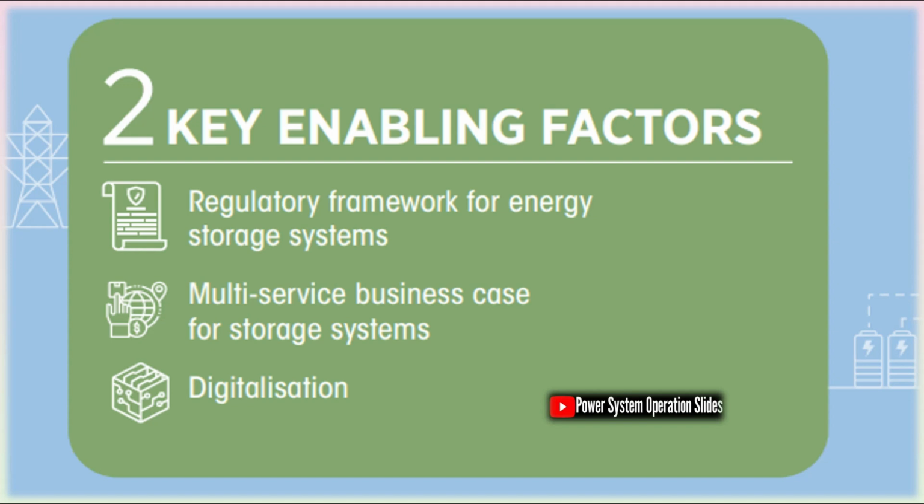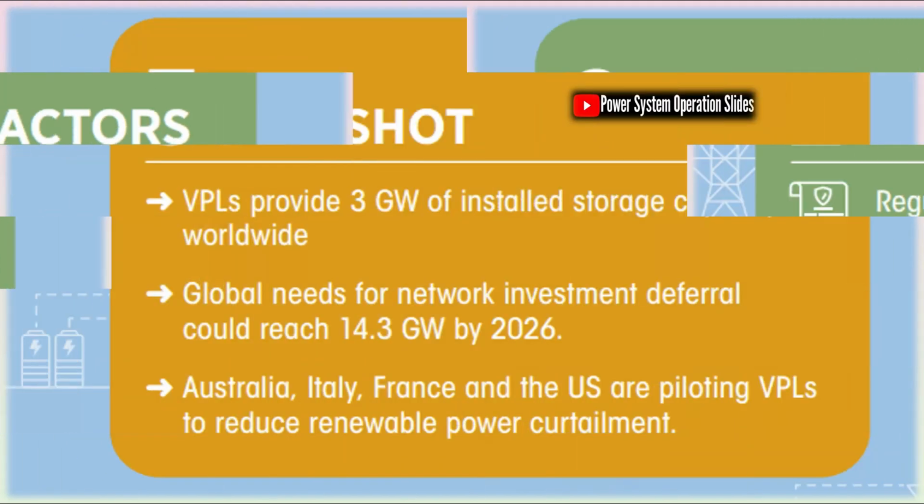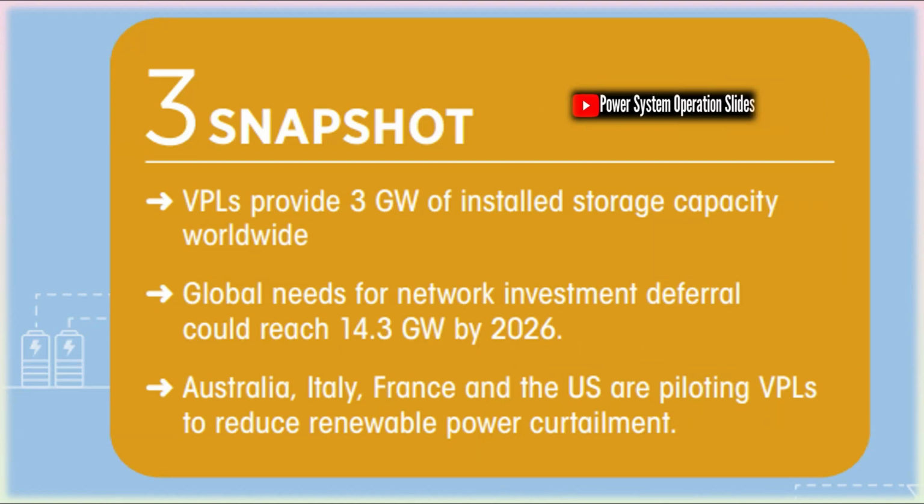Power electronics devices: FACTS, STATCOM, SVC, SSSC, UPFC, HVDC back-to-back or VSC links, and converter interfaces that can change power flows quickly. Energy storage systems, BESS, and controllable local DERs, solar plus inverters, used to inject or withdraw power at strategic points. Dynamic line rating (DLR) and adaptive protection to exploit temporary thermal headroom safely.